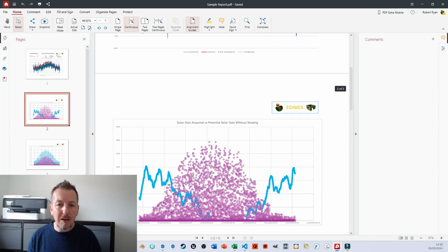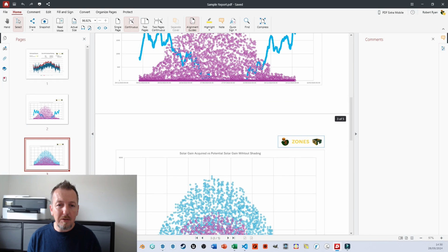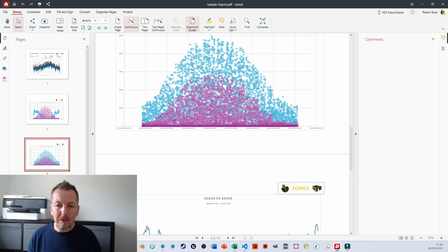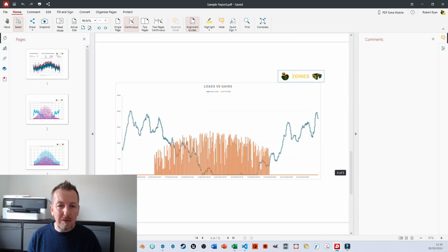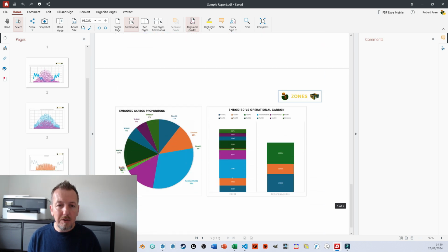Aside from overheating temperatures and heating temperatures, the program does the same dynamic calculation within the interface and prints reports for things like PV balance, heat load, solar radiation versus solar potential, and much more. And the program also has an integrated embodied carbon calculation and operational carbon. And all of this can be done from a very simple SketchUp model.